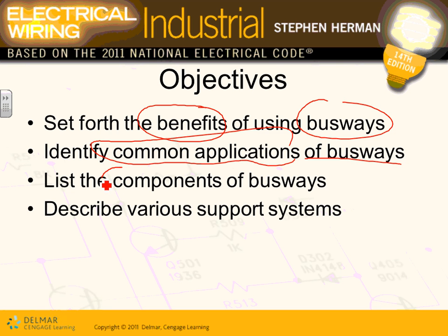Components of busways, we'll talk about that. What is a busway made of, in terms of elbows and angles and plug-ins, and various support systems? I don't know if you were paying attention to how they supported these busways. Sometimes you mount them against the walls or the ceilings, or you just bend them. There's a whole lot of hardware associated with mounting and supporting the busways. Busways are very, very heavy per foot.